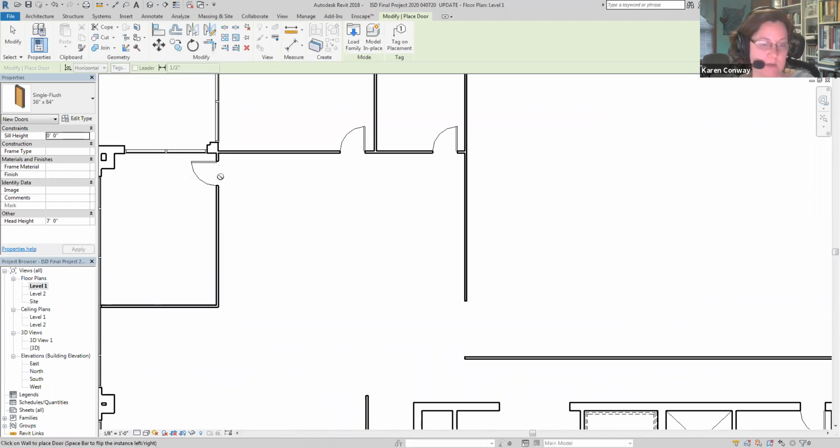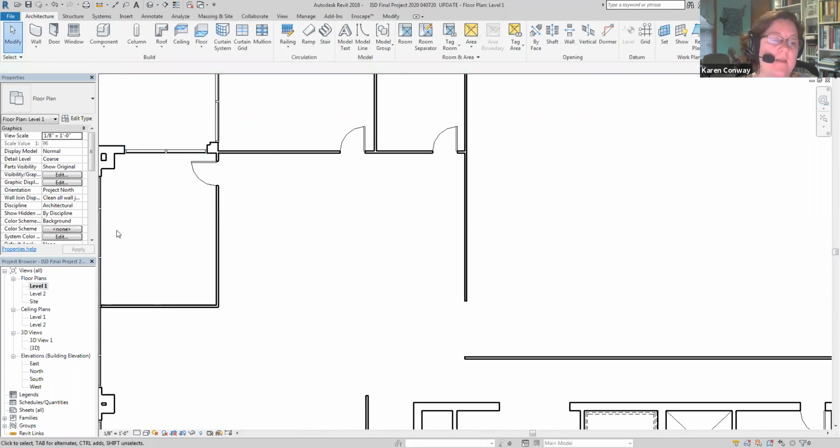Placing your doors, you're going to pay attention to the door swing. Again, you want to be able to swing the door this way and then have plenty of space here, so that you're not walking into a wall, so to speak. You also need to pay attention to what Anthony went over with you about having enough space to lead up to this door. If you were in a wheelchair, you need 18 to 24 inches for code to get in there.